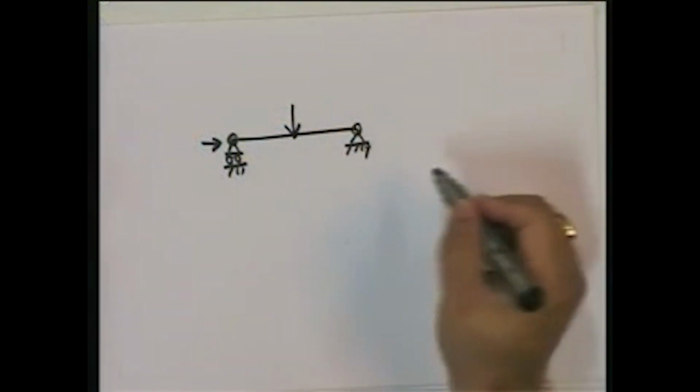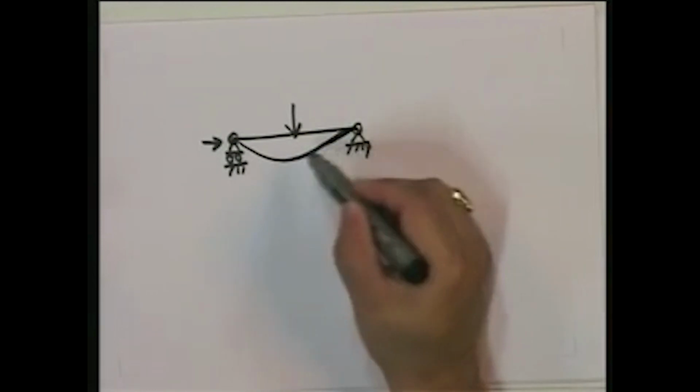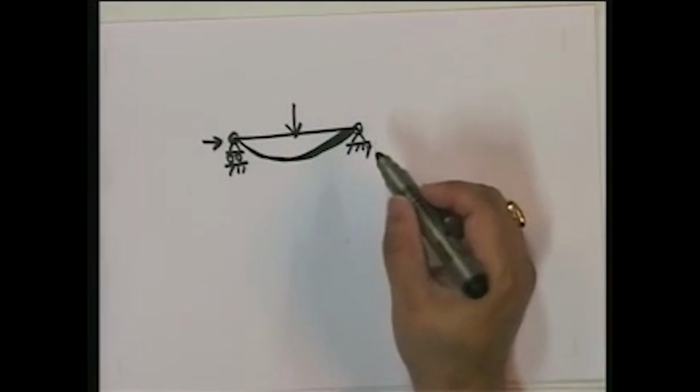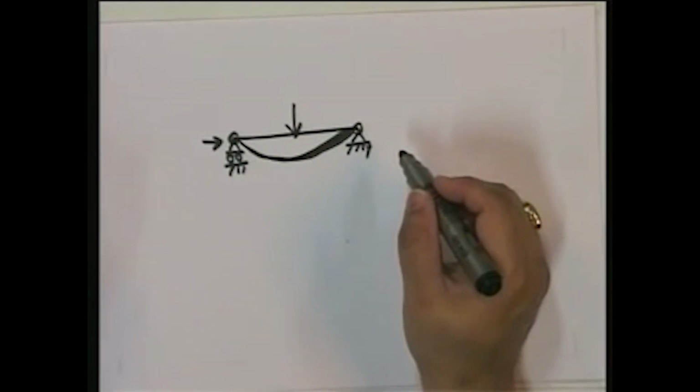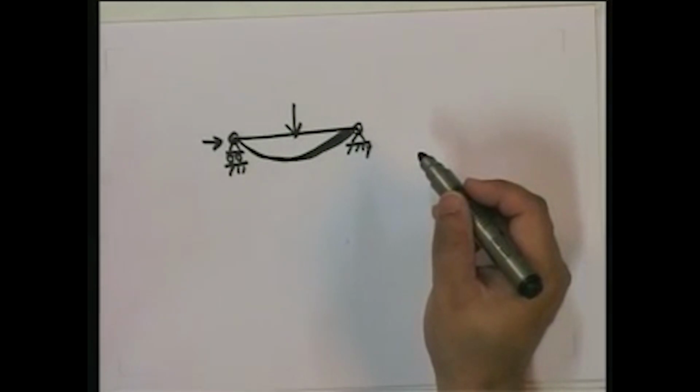No. Why? Because you have to understand the whole concept of a beam, the behavior of a beam, the way it's loaded. How is the beam loaded? It's loaded in this manner. What happens to the beam? The beam goes like this. You see? So therefore, the entire concept of displacement degrees of freedom for a beam and a frame would be different from that for a truss, and that is why we need to look at it differently.